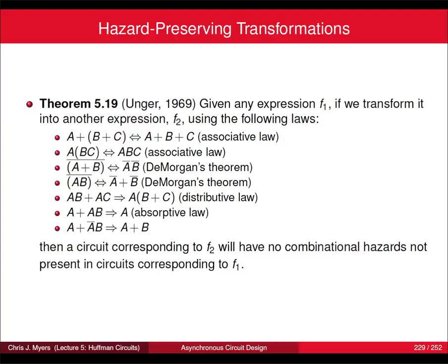So you have to put some constraints on your logic synthesis engine. Another thing that a multi-level logic synthesis engine will do is minimization as it goes. It'll try to do logic minimization. And you also have to shut that off. Because why would minimization be a problem if it tried to simplify your formula? The gate might become complex.